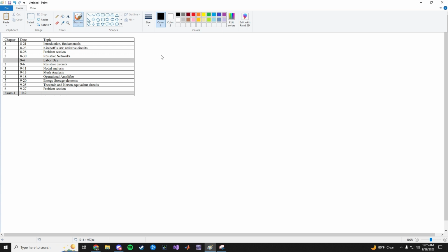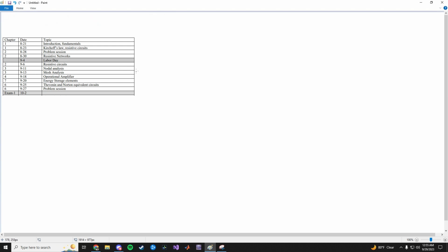So just to recap, resistor networks are basically just voltage sources, current sources, dependent or independent, a mixture of all of them, and only resistors. So remember, the 2 techniques to solve them are mesh analysis and nodal analysis. Those 2, pointing to resistor circuits. So those are 2 techniques you would use to solve resistor networks. So next are operational amplifiers, or op amps for short.